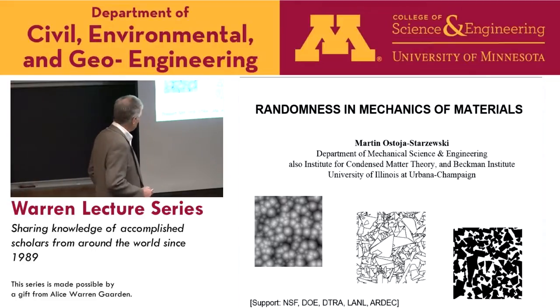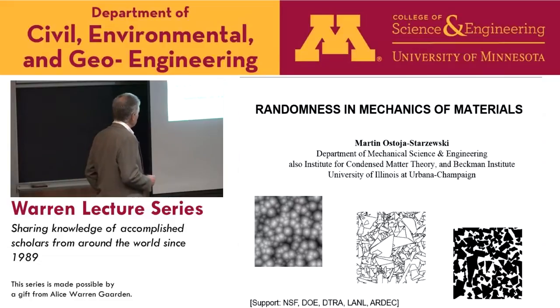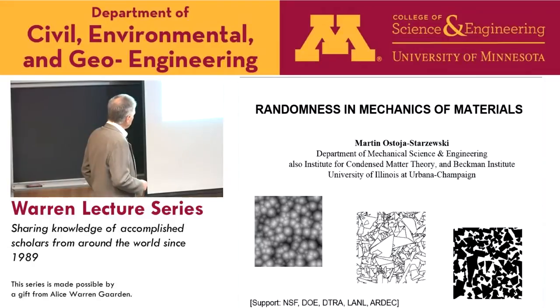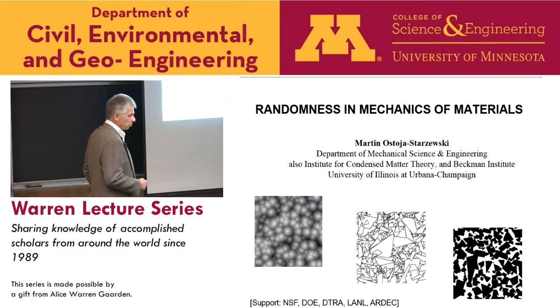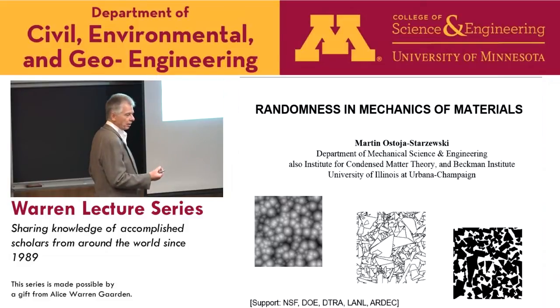So I will talk about some issues in mechanics of random media, starting with the problem of passage from a random microstructure, such as here some matrix-inclusion composite with random distribution of inclusions, to a homogeneous continuum. And this is what we want in conventional continuum mechanics, some continuum model which hinges on the concept of representative volume element, RVE. This is the same thing as the dV element in continuum mechanics, over which we postulate that we can take gradients and such when we localize balance equations.